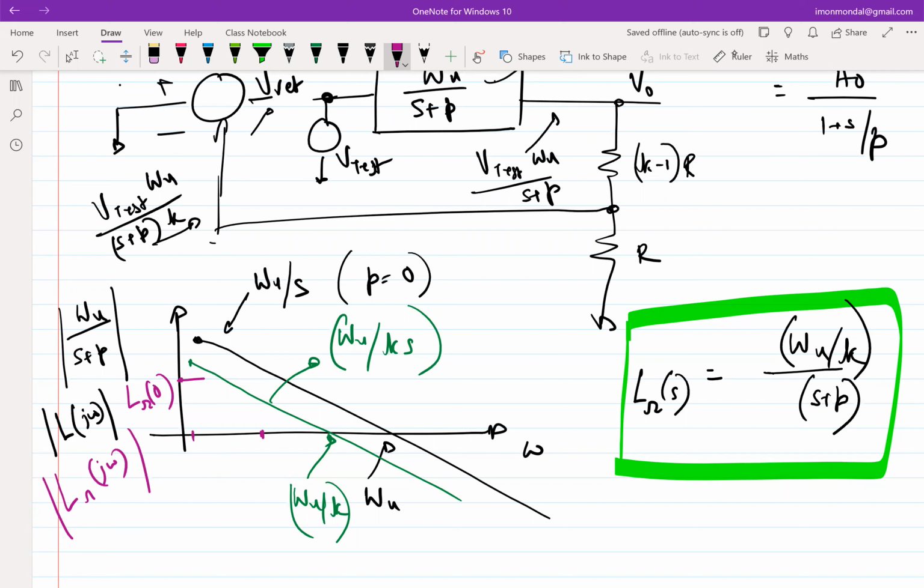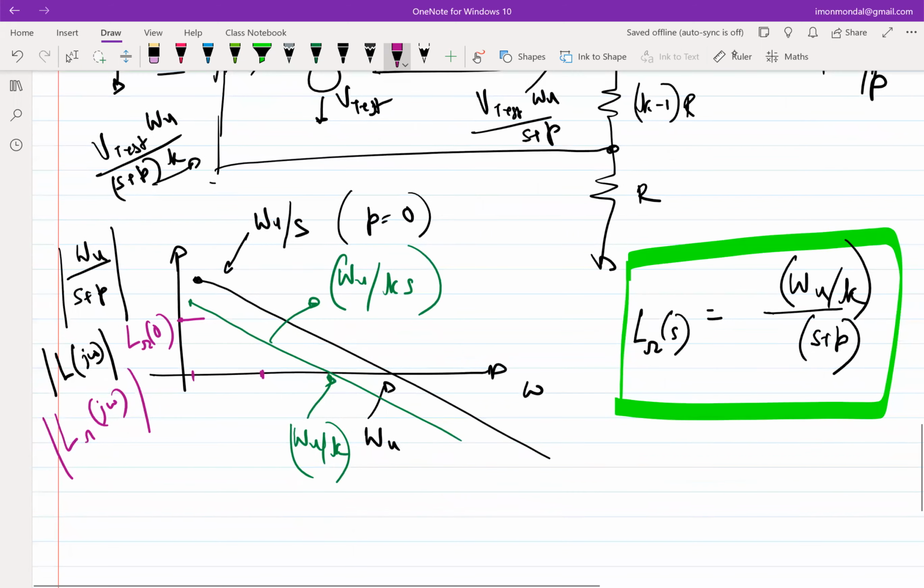So if you use Bode approximations, what is Bode approximation? It is the fact that you can use straight line segments to define your gain transfer functions before and after a pole. Okay, so let's assume that we have crossed the pole P, wherever the pole P might be. What will the transfer function look like when I have crossed the pole P?